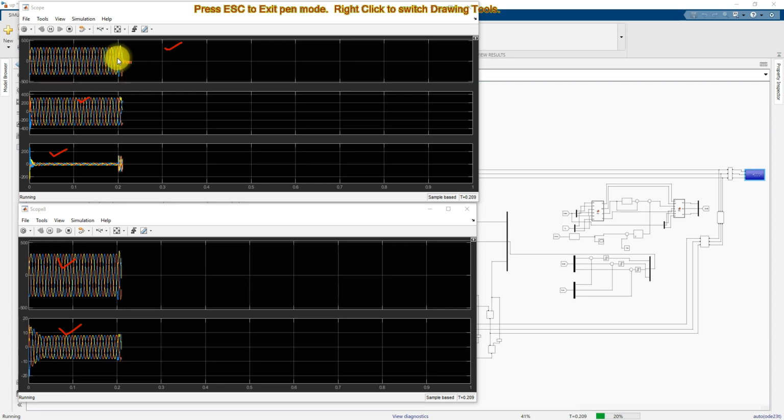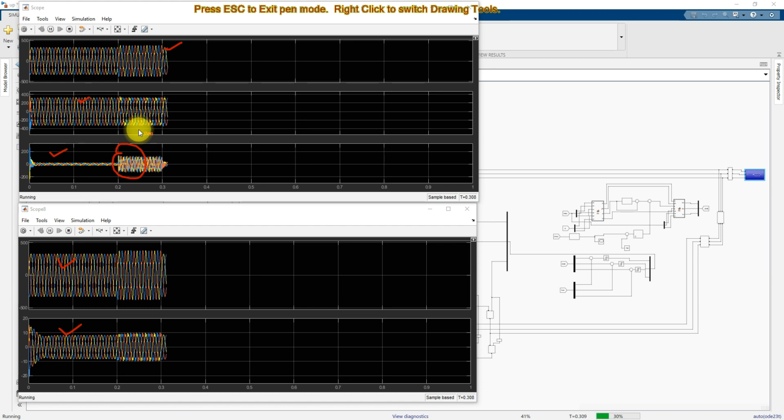So here you can see that we are injecting the harmonics in the grid. Here you can see that it is injecting some voltage in order to alleviate that problem. Here you can see that we do not get an exact sinusoidal because of that harmonic problem. But it reduces somewhat, right, by using that DQ0 control along with the PQ control in the shunt active